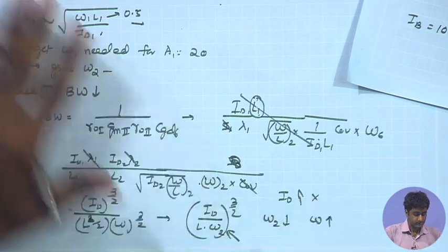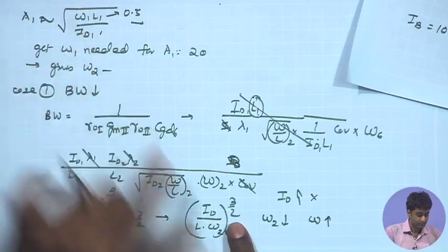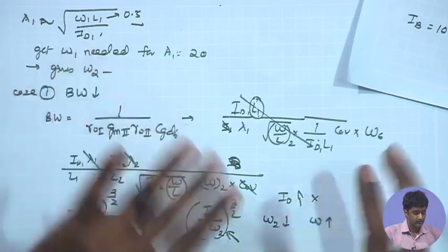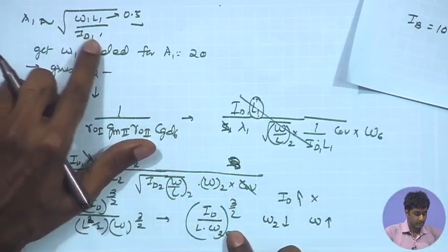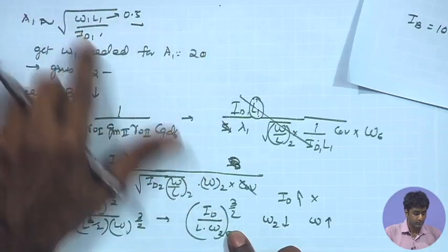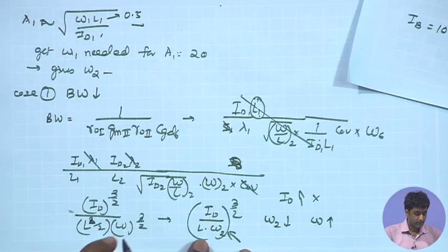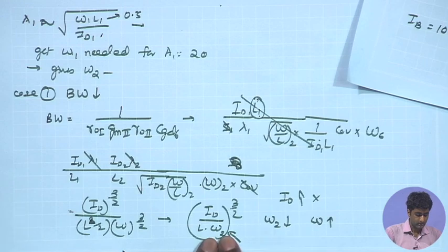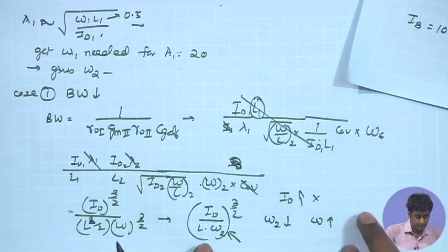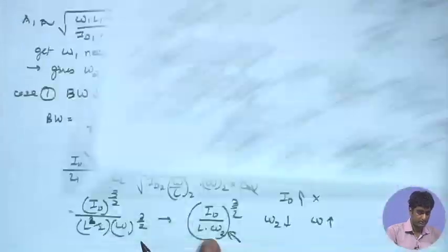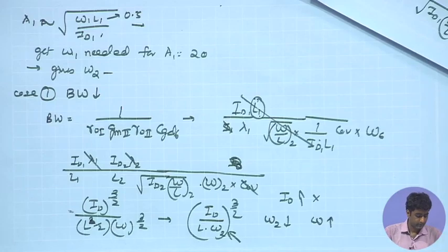So we can see the directions to be taken up. Since the overall gain can be bifurcated in an uneven fashion, I can try to divert more gain toward the first stage and lesser toward the second stage, and try to push the pole towards higher frequency by choosing a W2 which is smaller, because a smaller W2 would imply a smaller CGD and hence lower Miller multiplication and higher bandwidth. So this is another concern that we can have.